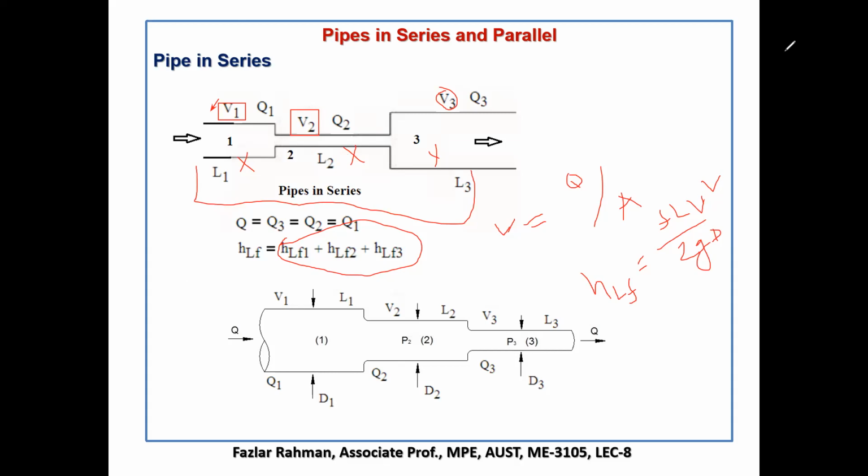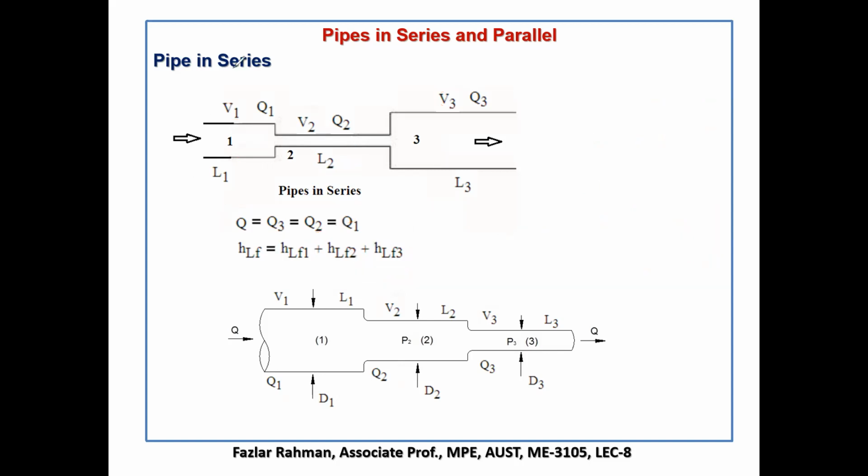It's the same thing. For example, you have several electrical resistances in series. What will be the resultant? Resultant R will be R1 plus R2 plus R3, right? So same thing in the fluid. And if you study, there is one course called fluidics or fluid power control. This frictional loss in the flow, they represent like R1, R2, R3, like electrical resistance.